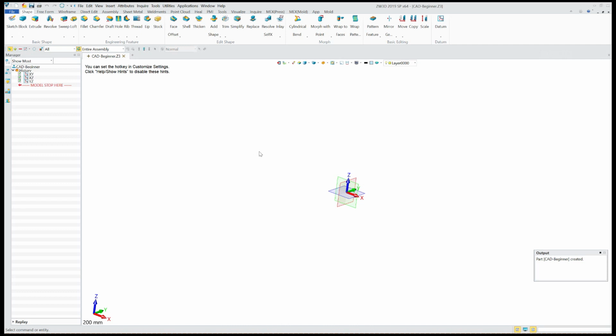And when we design and construct geometry, we normally want to control it with dimensions so that we can design to specific values. And that's where we use sketches. So to create a new sketch in ZW3D, we click on the sketch icon in the top left corner.